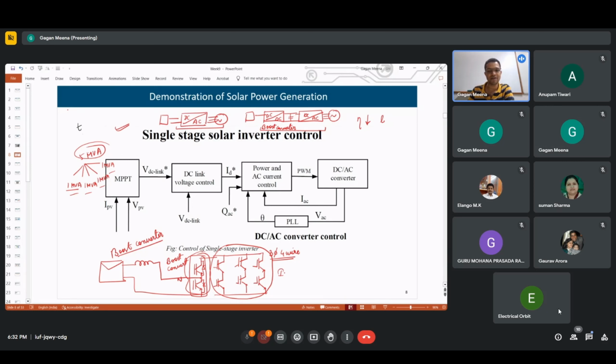So here also we are transforming to make our life simple, because in ABC, doing three-phase short circuit analysis is very complicated. So we are converting it into the phase sequence domain, so we get three different systems. We can do the same analysis which we were doing on a single phase. If it is a balanced system, we do per phase analysis. So here we get three balanced systems.